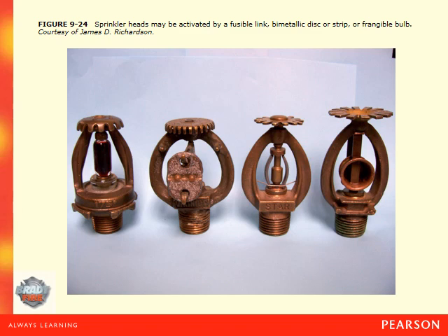They can have fusible links, as we said earlier, such as these, or they can have some sort of glass, fluid-filled frangible bulb. Basically that fluid is designed to boil and expand at a certain preset temperature. And once it does that, it breaks the glass, again allowing for an opening in the orifice for water to exit the system.